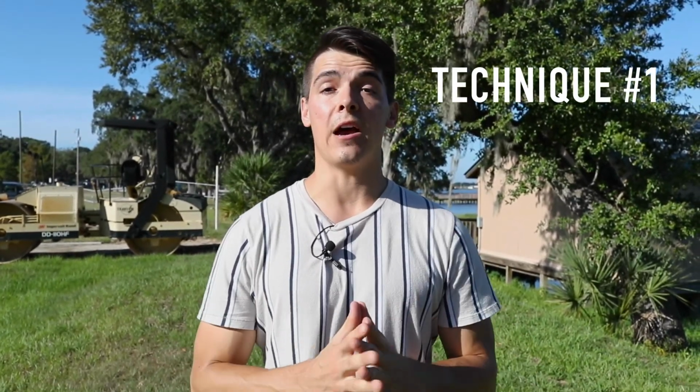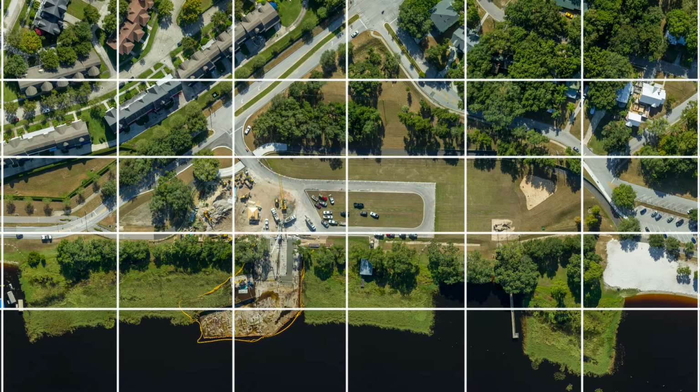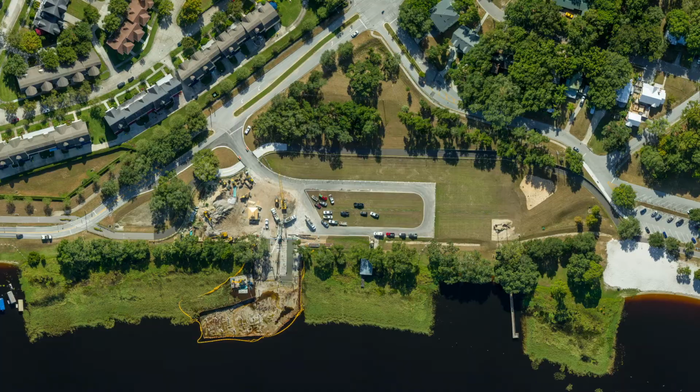So now that we've talked about gear, let's get into the 5 techniques I use to drone this construction site. Okay, so the first technique is the photo merge. Now, you might be asking what a photo merge is. Here's an example right here. It's basically 40 to 50 images top down at 400 feet, covering the entire surface area of the construction site.